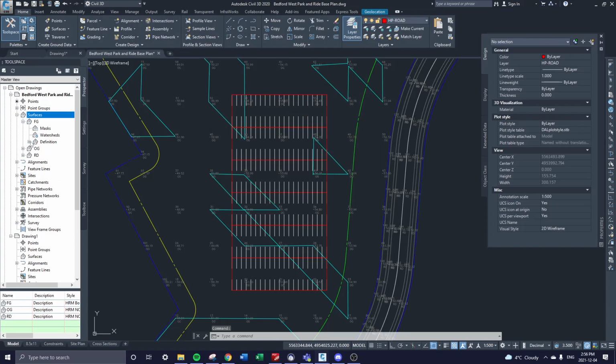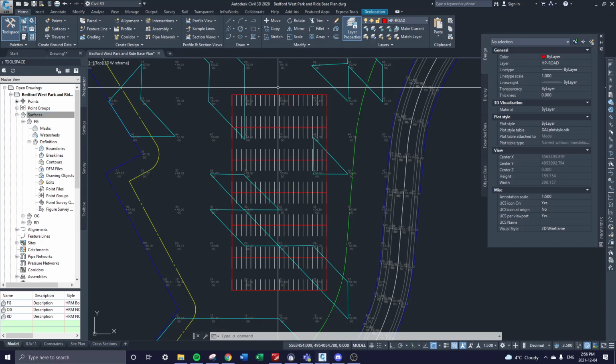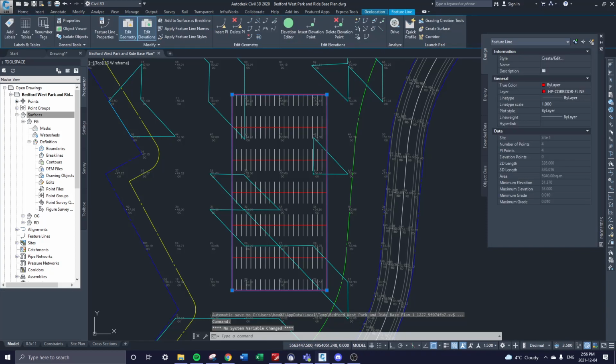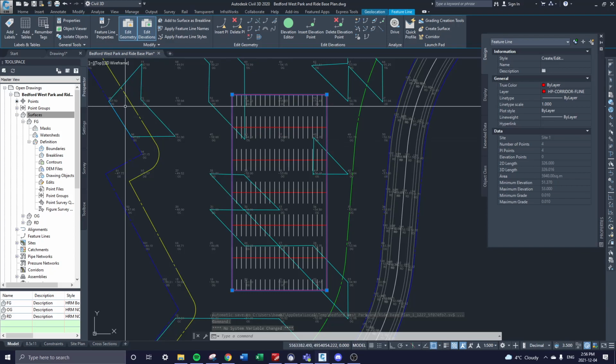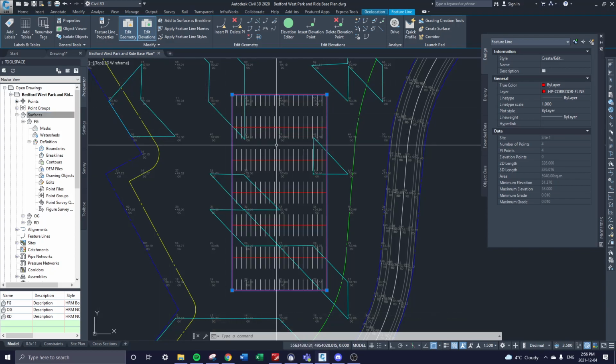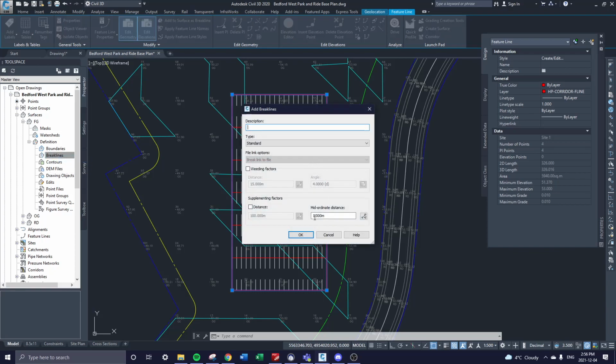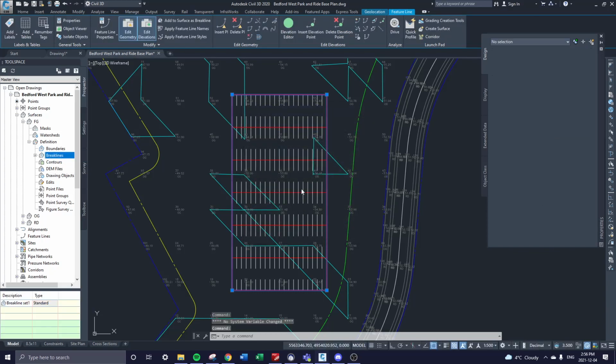And you might have guessed it, very similar to assignment 4 question 2. Except now we're the ones that created the elevations instead of importing points. So that feature line rectangle that you've manipulated into however you want, we're going to add as a break line. So hit OK. Okay, cool.